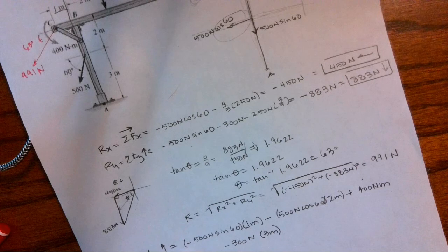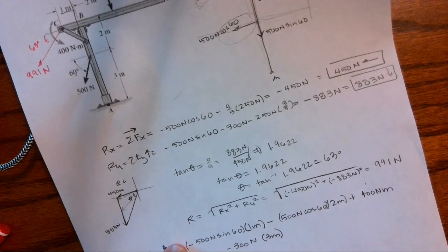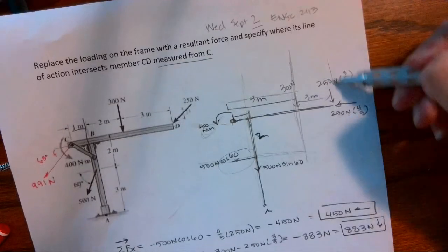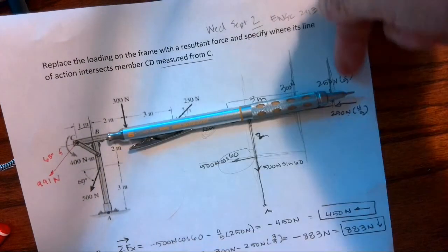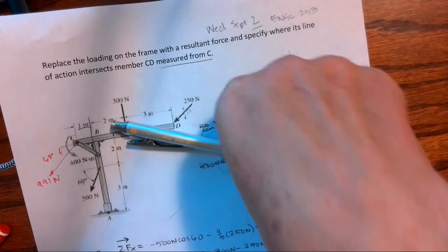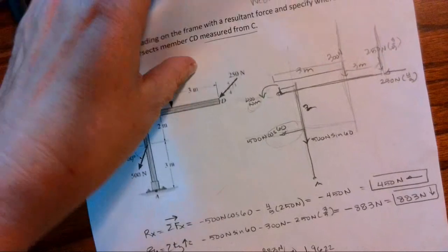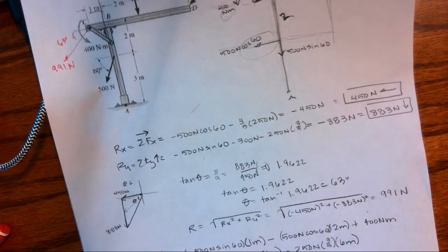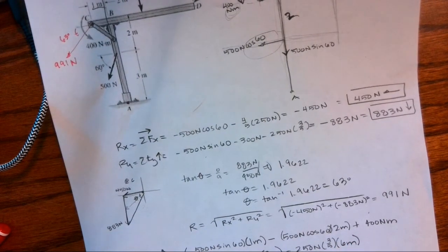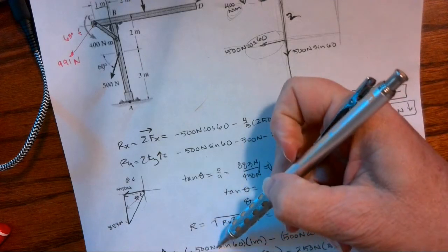And we're going to keep walking around our system, and you should find that we have the y component over here. If this is my clock handle again, pushing down, it's causing negative rotation. So I have negative 250 newtons times 3/5, and its perpendicular distance is 6 meters. So I have a negative 500 cosine 60, 1 meter.